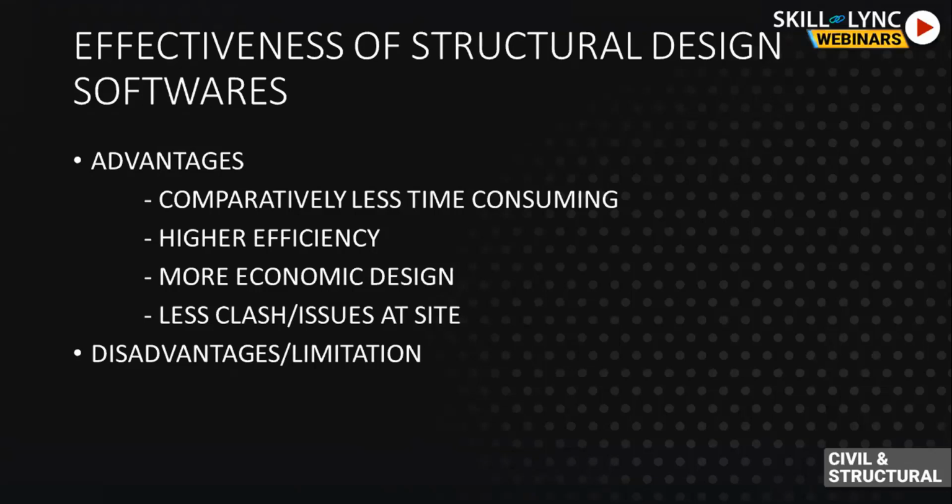We can have that model, rotate it in 3D and visualize that there will be no clash. Also, if there is a clash that we cannot see with our naked eye, that we miss, the software will be able to identify that. The software will tell you that there are 15 clashes. If there is lesser headroom, as I've mentioned that in a 1.5-meter height room you cannot move freely, the software will be able to highlight that also.